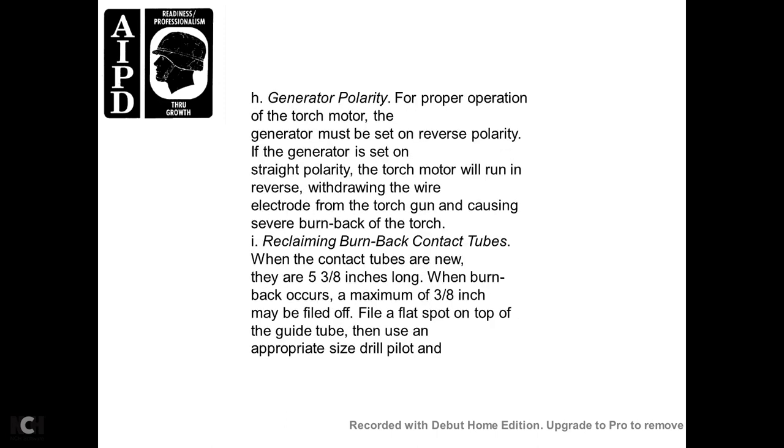Generator polarity. For proper operation, the generator must be set on reverse polarity. If the generator is set on straight polarity, the torch motor will run in reverse, withdrawing the wire electrode from the torch gun and causing a severe burn back over the torch.